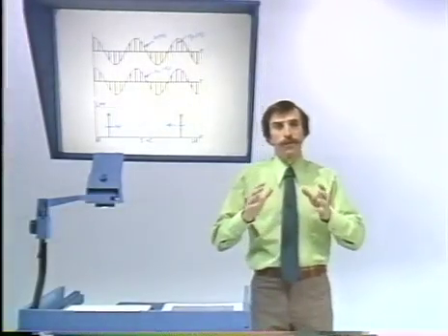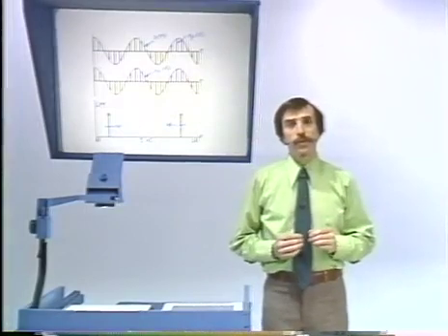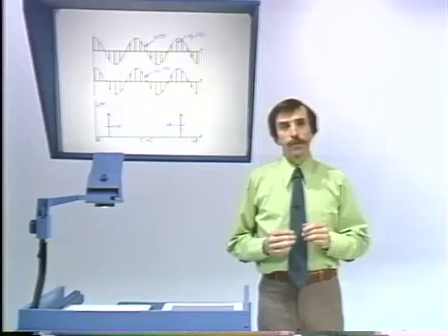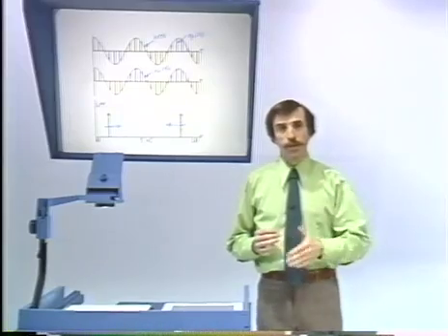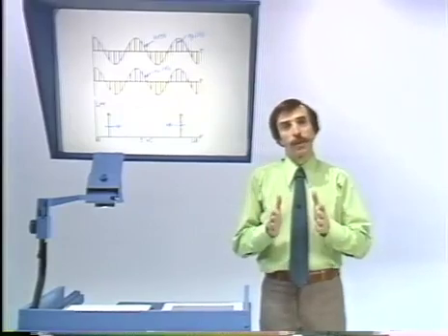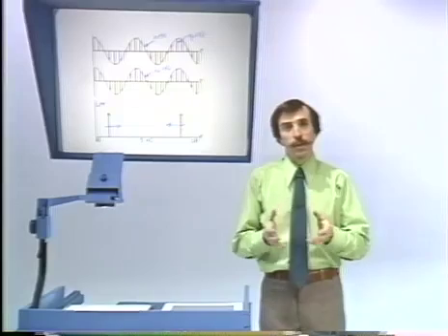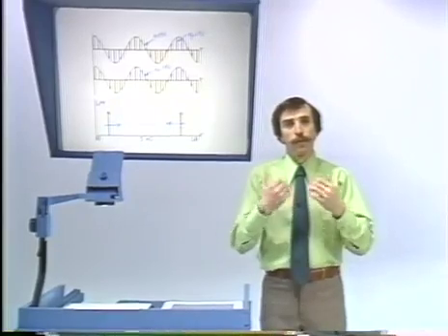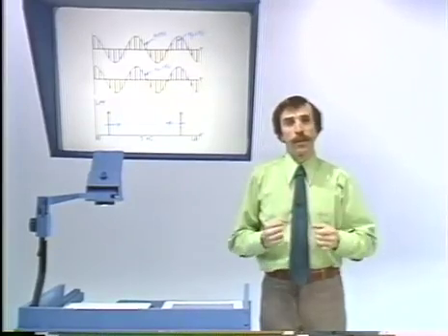So we've sampled a signal and then reconstructed the signal from the samples. And keep in mind that given a set of samples, there are lots of continuous curves that we can thread through the set of samples. The one that we picked, of course, is the one consistent with the assumption about the signal bandwidth. In particular, we've reconstructed the signal whose spectrum falls within the passband of the filter.